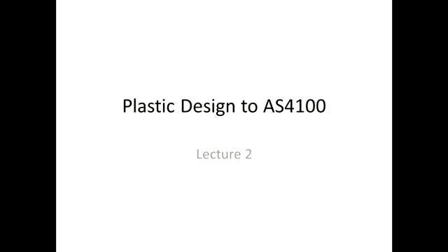And so if we can determine the equal area axis, how do we define the plastic section modulus? I think we said that to determine the plastic section modulus, we have to take the first moment of area about the equal area axis.